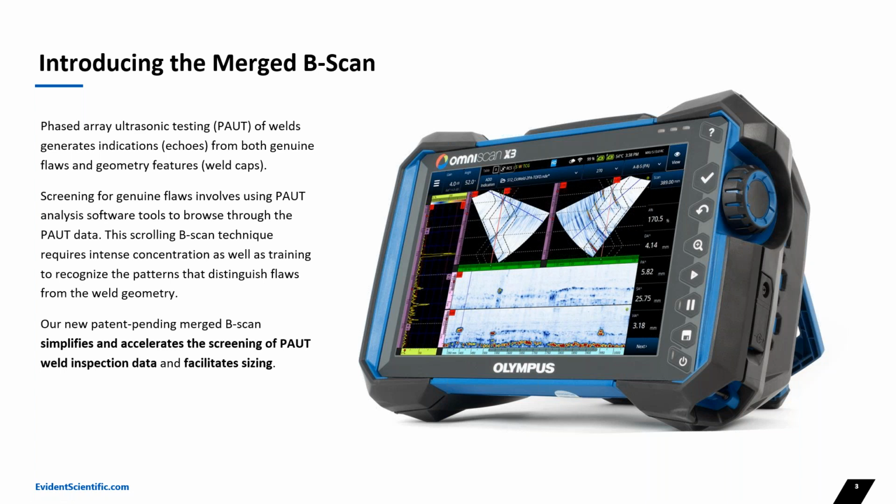So we recently introduced that new functionality called the merge B-scan. This is actually a very, very simple functionality, but unbelievably, it seems that it was not in use earlier. We decided to file a patent for it. The main benefit of this functionality is that it simplifies and accelerates the screening of phase array weld inspection.